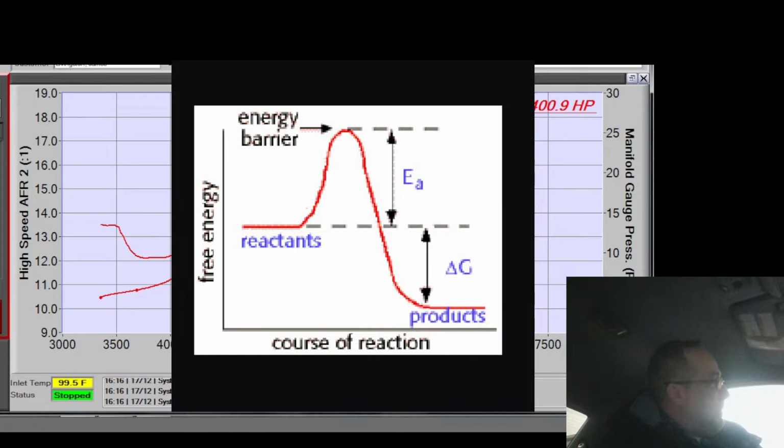What am I trying to say? So the burn speed is affected by the proximity of the molecules. The closer they are, the more likely they are to transmit their power, exchange energy to the neighboring molecules, exceed the activation energy, and propagate the burn in the cylinder.